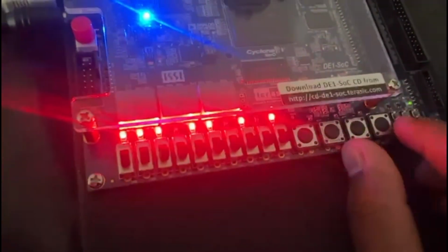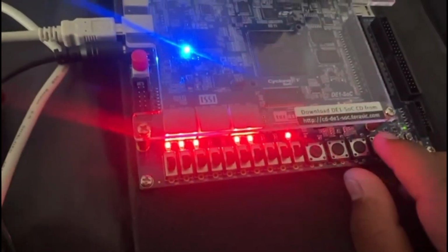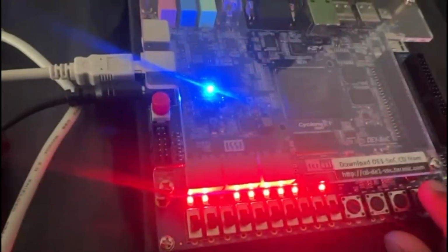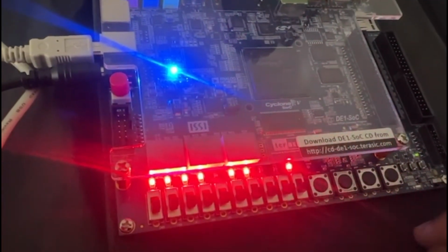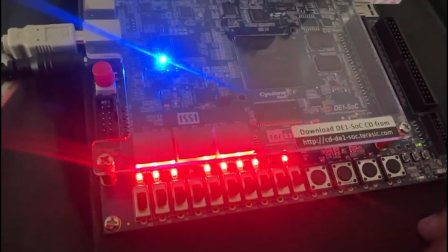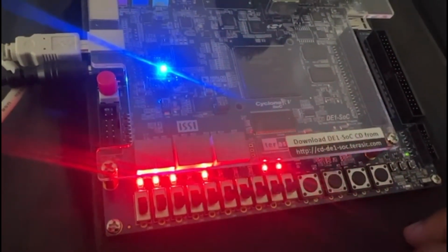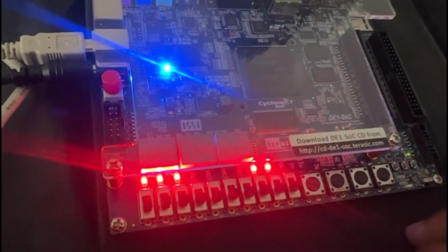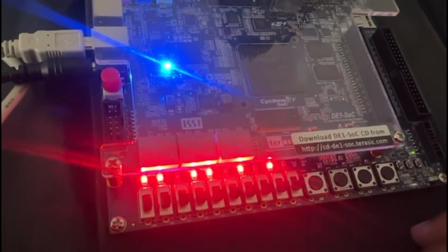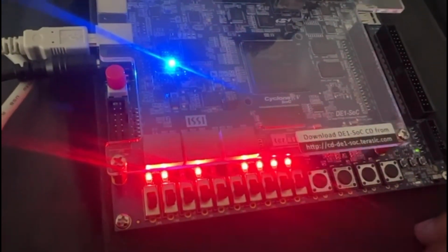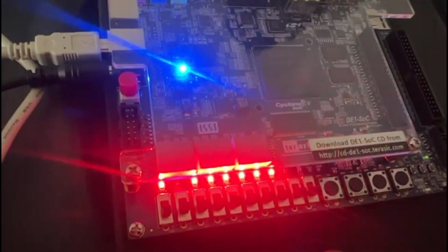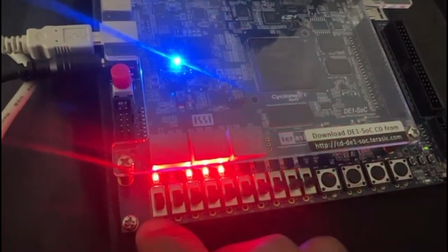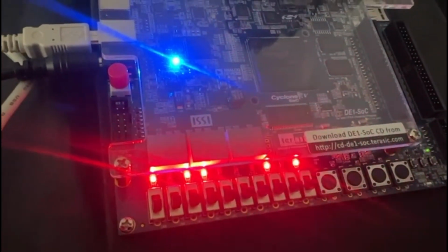And then we'll click on the reset button to verify that all the 10 LEDs are doing the up counting and down counting. You can look at the LEDs, it's so fast. This is because we are not looking at just the last 4 MSBs, we are looking at the last 10 MSBs. And this is actually down counting because the direction is towards down, or it's low.